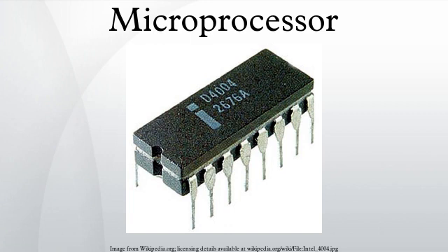The 8086 and successors had an innovative but limited method of memory segmentation, while the 80286 introduced a full-featured segmented memory management unit. The 80386 introduced a flat 32-bit memory model with paged memory management. The Intel x86 processors up to and including the 80386 do not include floating-point units. Intel introduced the 8087, 80287, and 80387 math coprocessors to add hardware floating-point and transcendental function capabilities to the 8086 through 80386 CPUs.